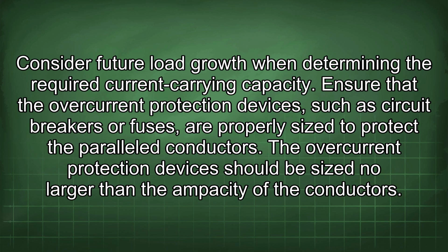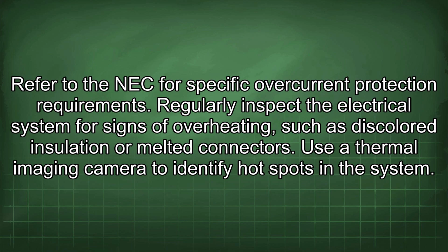Ensure that the overcurrent protection devices, such as circuit breakers or fuses, are properly sized to protect the paralleled conductors. The overcurrent protection devices should be sized no larger than the ampacity of the conductors. Refer to the NEC for specific overcurrent protection requirements.